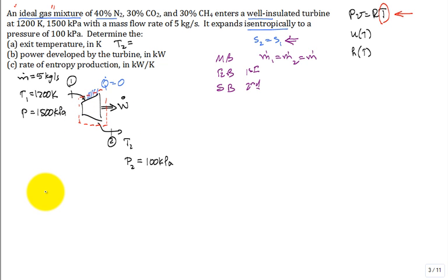what do we pick up? I know we can do it in 2 or 3 steps, but that first law gives us something like the power out of the turbine, out that control volume, out that shaft, is equal to the mass flow rate times the enthalpy in minus the enthalpy exit. Have you done the first law enough for turbines that that looks good? Yes. But you've got to go back to the basic equation, apply it, manipulate, simplify, and get that with confidence.